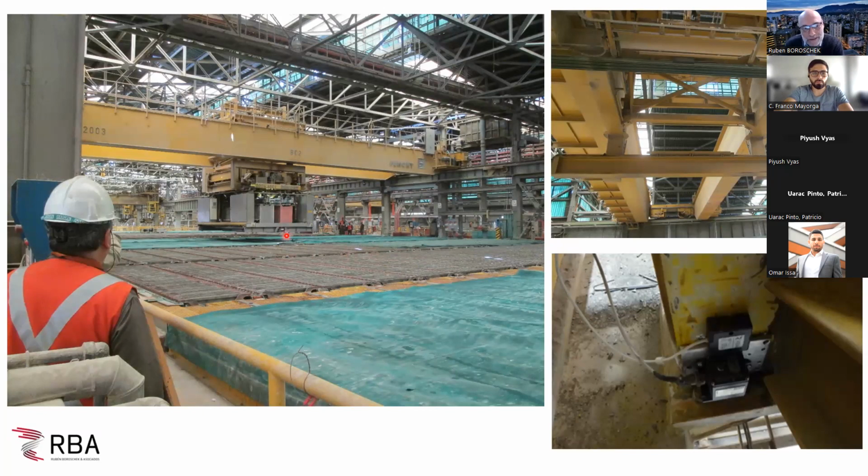So the problem here was that this traveling crane is pretty big, you can see here, I think this is 400 meters long. So it was moving too much on the rails due to deformations on the structure. So we installed several sensors on the traveling crane to detect where the irregularities of the structure generated motions on the crane. And some of these motions were so strong that some of these plates were released and fell.